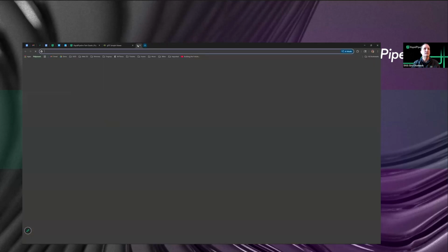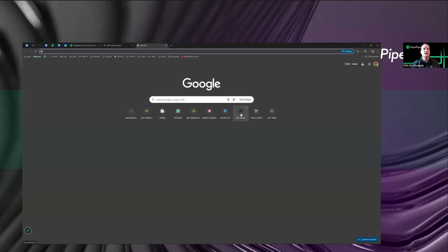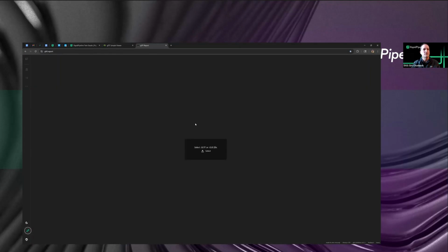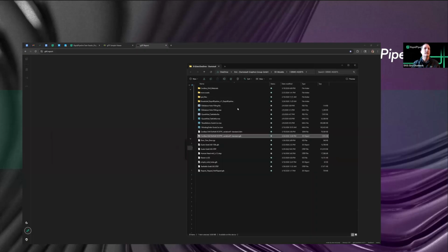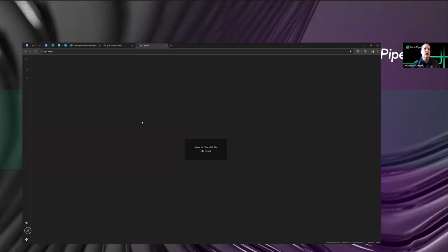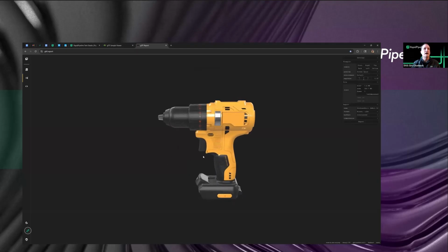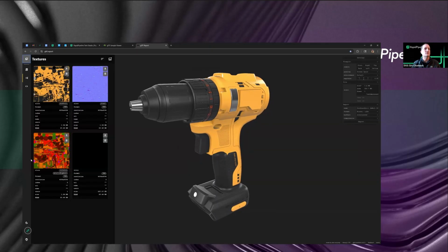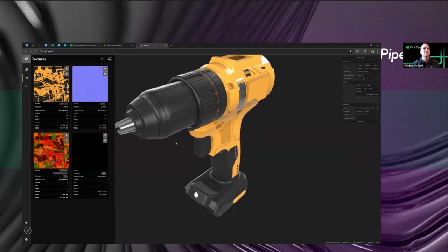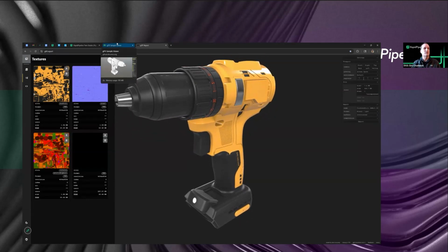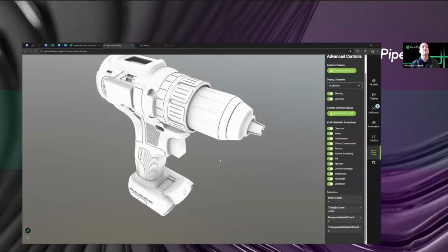The other thing we can do too is look at something like glTF Report, a really cool tool built on Three.js by Don McCurdy. It's a really cool tool for examining mesh data in glTF format. So when you drag a glTF file in here, it has a nice render view, but you can actually look at the textures too and see how the textures are made. So it's got a base color texture. It's got a normal map, which is cool. It's actually baked normal map data from the high-res source onto the low-res decimated file. So we can actually look at it here.